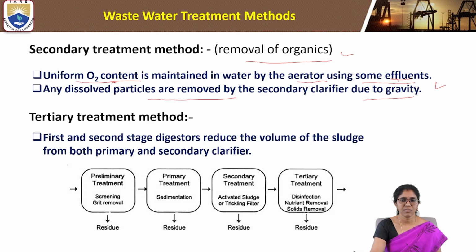For the removal of organics, we are using oxygen. By using oxygen, these organics can undergo oxidation, and here we will get some undissolved particles. Any undissolved particles are removed by the secondary clarifier by using gravity, due to gravitational force.